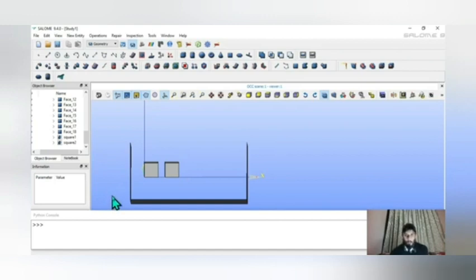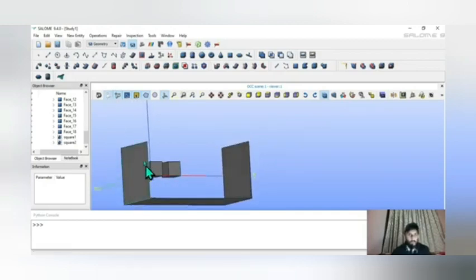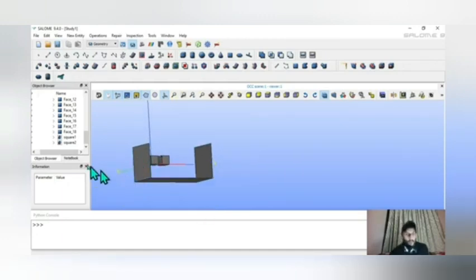You can do this grouping for the other faces as well, the bounding box. For example, if you're running a simulation in the aerodynamic aspect, you can put this face as your inlet, this as outlet, and then walls maybe the other ones. But we are not trying to do that at the moment, we are just trying to show how automation works. So up till here it's fine, right? So now let me just quickly save it as.